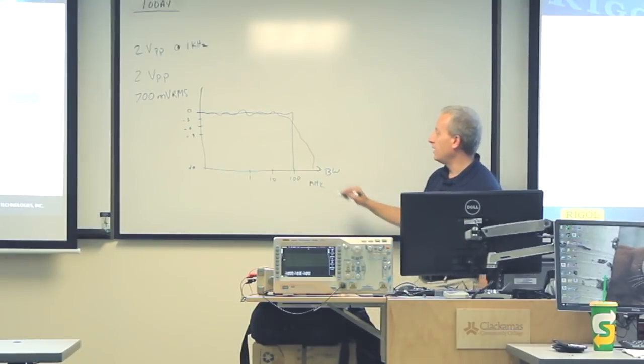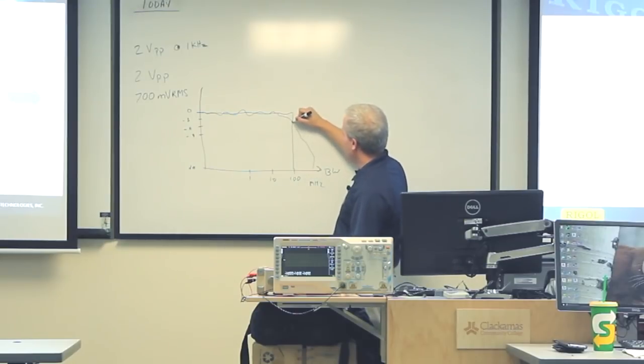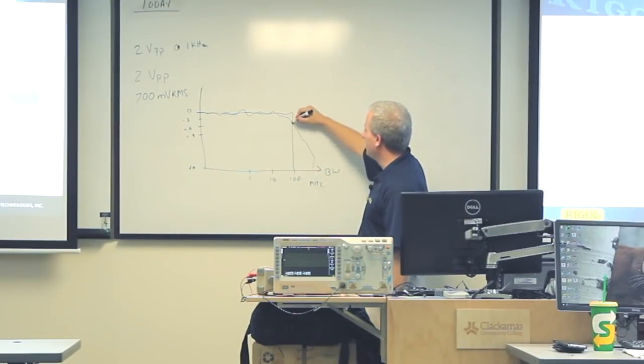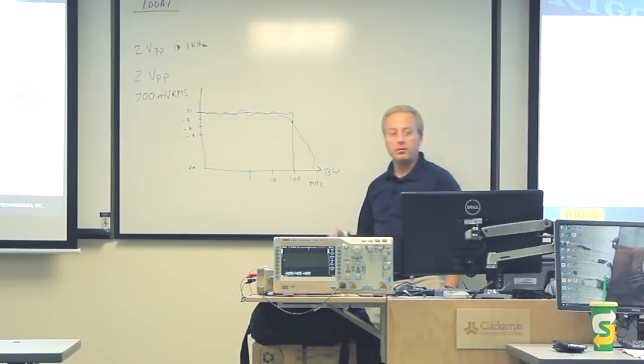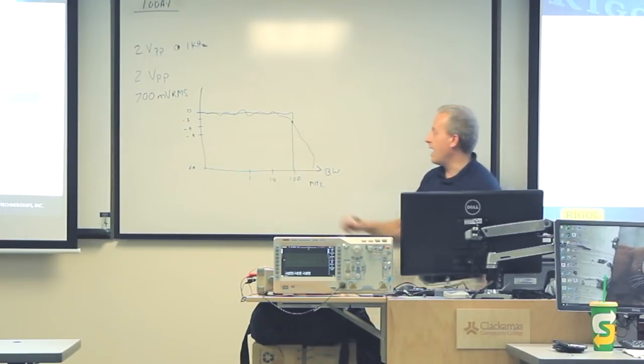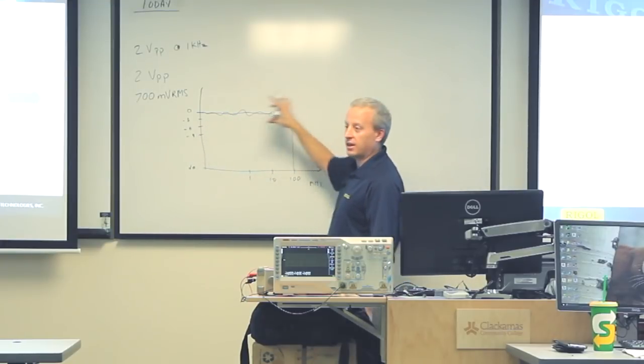So when we talk about a 100 megahertz scope, or whatever bandwidth, what the person telling you that is actually saying is that at 100 megahertz, this scope only attenuates the signal 3 dB. And from DC to there, it should never be outside of that 3 dB band.